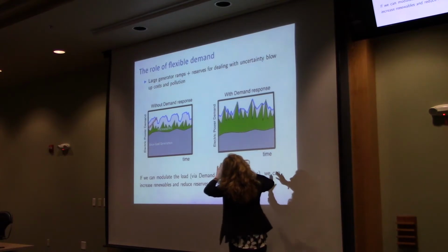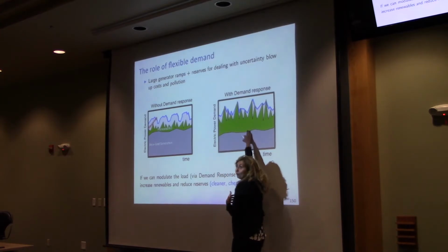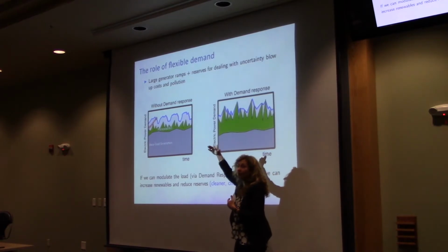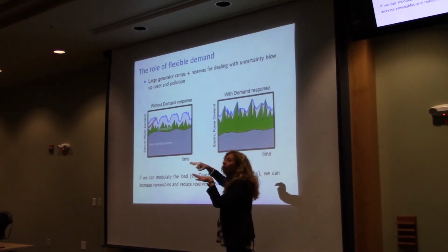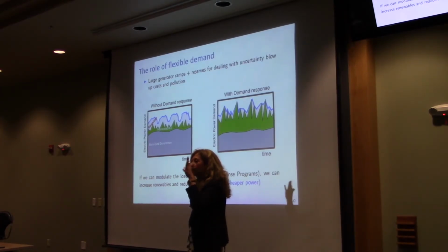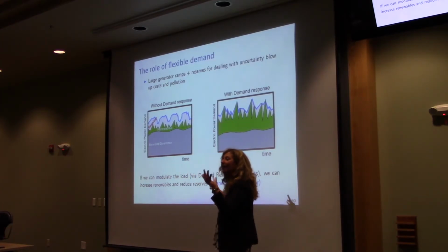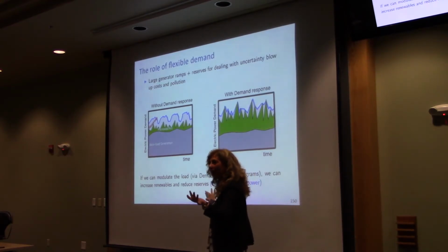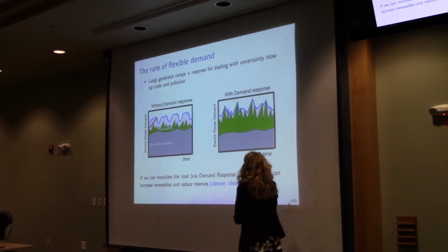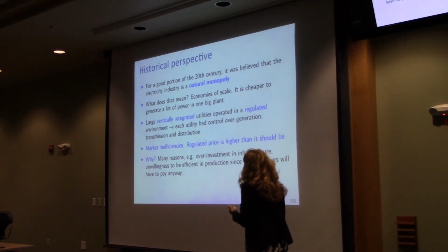So with demand response, what you want to do is shape the demand so that it looks more like the renewables. And then you can put in more renewables and decrease the base load. And so here you can use less coal, right? So that's really, aside from the cost of the solar panel and the installation, et cetera, these are the system levels, what demand response is supposed to do. This is why we want the ZigBee in your personal area network to do anything to help climate, or the AMI, or anything, right? That's really what we want to do. We want to shape the demand so that you can follow renewables, so you can put in more renewables and have cleaner and cheaper power. So now how do these markets work?